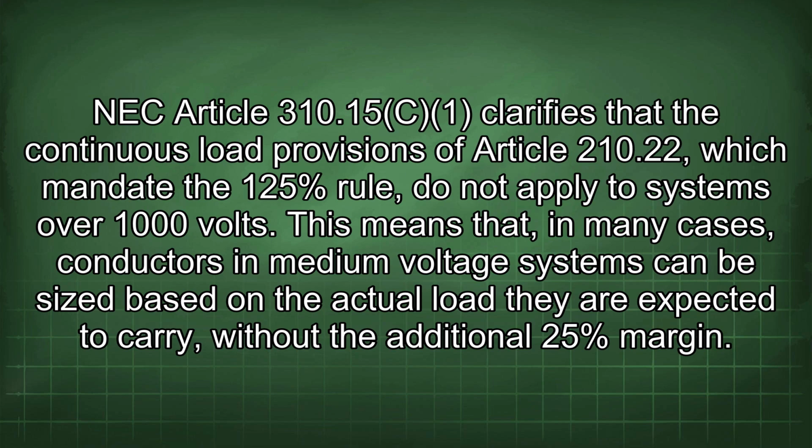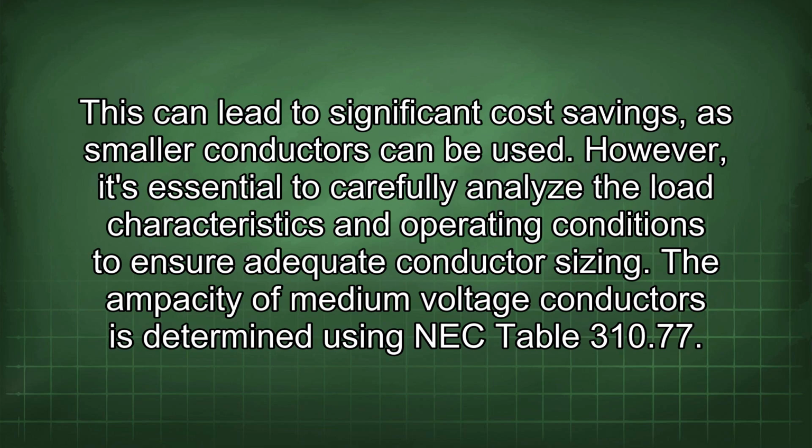This means that, in many cases, conductors in medium voltage systems can be sized based on the actual load they are expected to carry, without the additional 25% margin. This can lead to significant cost savings, as smaller conductors can be used. However, it's essential to carefully analyze the load characteristics and operating conditions to ensure adequate conductor sizing.